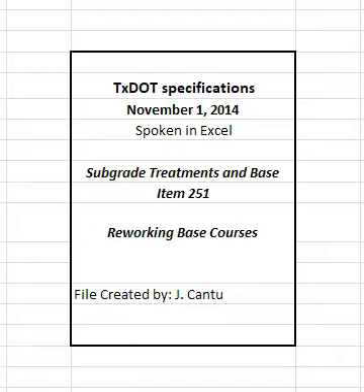4.2.2 Salvaging. Remove the existing base material and stockpile. Windrow if allowed. Perform salvage operations without interfering with traffic, proper drainage, or the general requirements of the work. Remove scarified material using a method approved by the engineer. Keep material free of contamination.